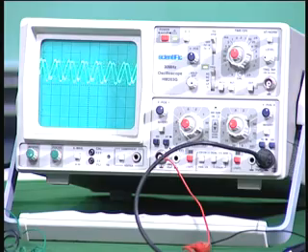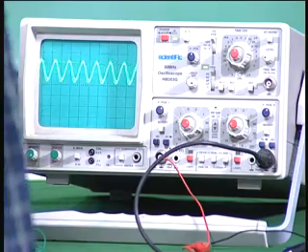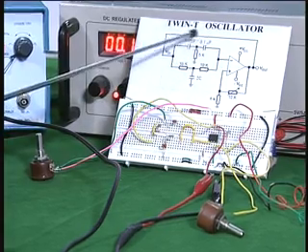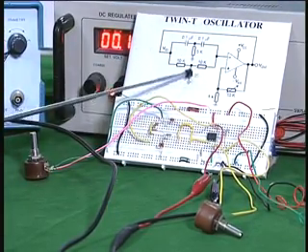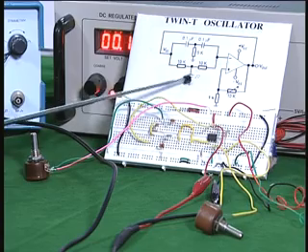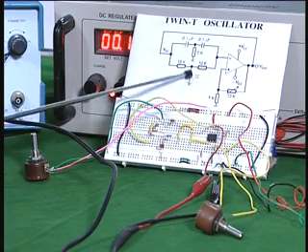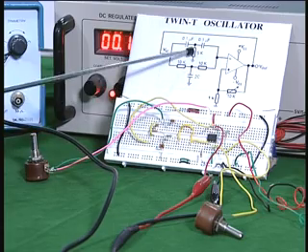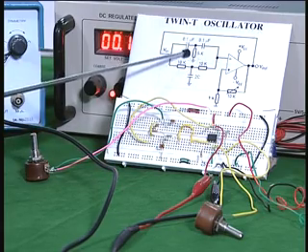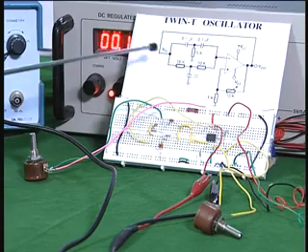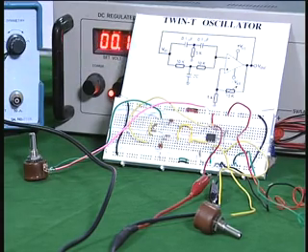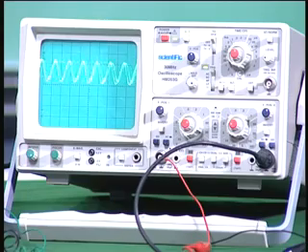So, the values of resistors are 10K and 0.1 microfarad. This is 10K, the 2 resistors, and the capacitors are 0.1 microfarad, and therefore, this will be 2C, that means 2 times 0.1, 0.2 microfarad. They have put parallel capacitors there to add, and this is 5K, they have put again resistors in parallel to make this 5K, or you can use 4.7K. So, you find a very simple sinusoidal oscillator can be constructed using twin T network.